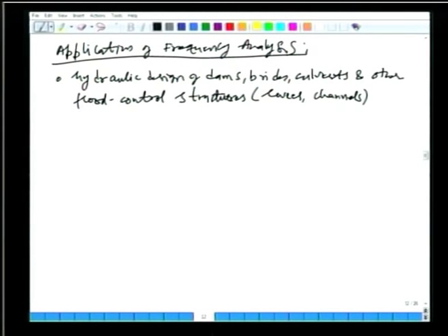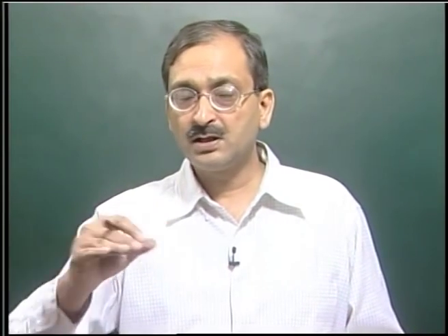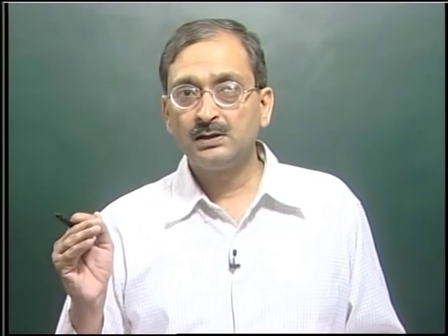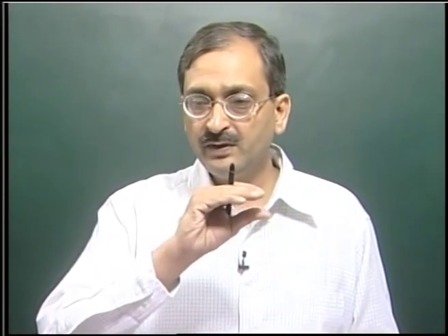So, what do we mean by this? When we say that frequency analysis is useful in hydraulic design, you know how we design a hydraulic structure, for example, a dam or a bridge. Let us say you want to build a dam or a bridge across a river. The bridge is normally designed for some magnitude of the peak discharge which we want it to pass through safely.